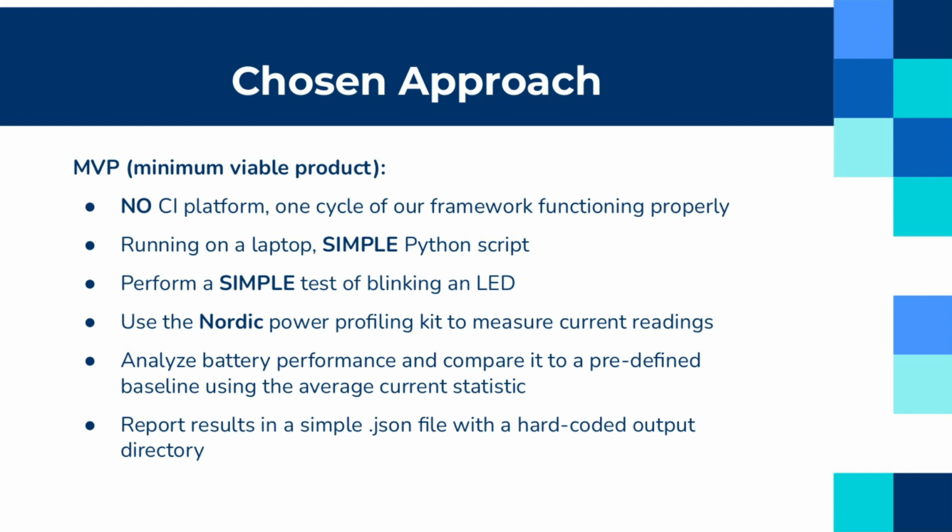At first, we did invest a lot of time into understanding embedded systems programming to generate a baseline program on the TI CC2650 using their IDE, CCS. This program served as the firmware of the device, but we figured that we needed to concentrate on the development of our battery analyzer script, not necessarily the hypothetical firmware update. The user runs the script from their laptop with their DUT connected to a JTAG controller, using relays to help load the firmware without directly connecting to the computer, which could interfere with the sensitive readings.